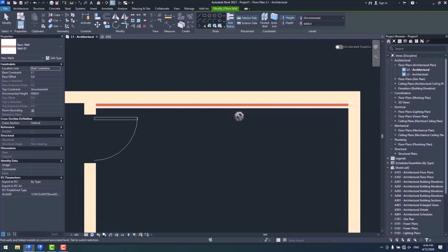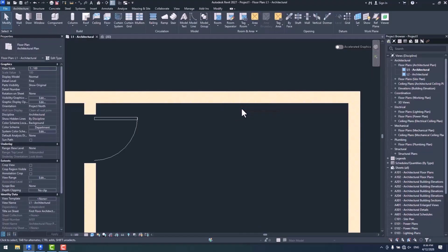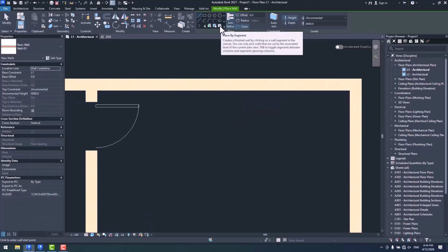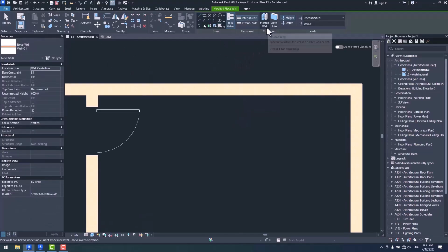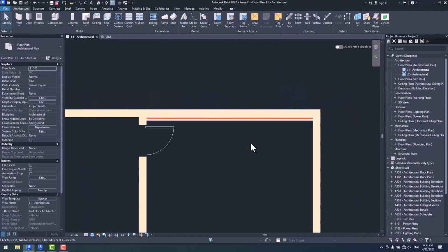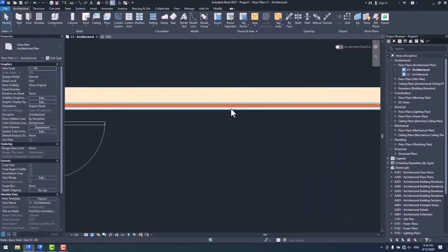Alright, as a very interesting item added to Revit in the new version, guys, we can mention hosted walls. For further elaboration, when we are working with walls, and to be more precise, when dealing with place-based segment, we would be able to activate this item. Let me demonstrate. I'm going to click on this wall, and you might say, alright, then nothing happened, right? Well, wrong. That's not true. What has happened is that this second wall here is now hosted on the first one.